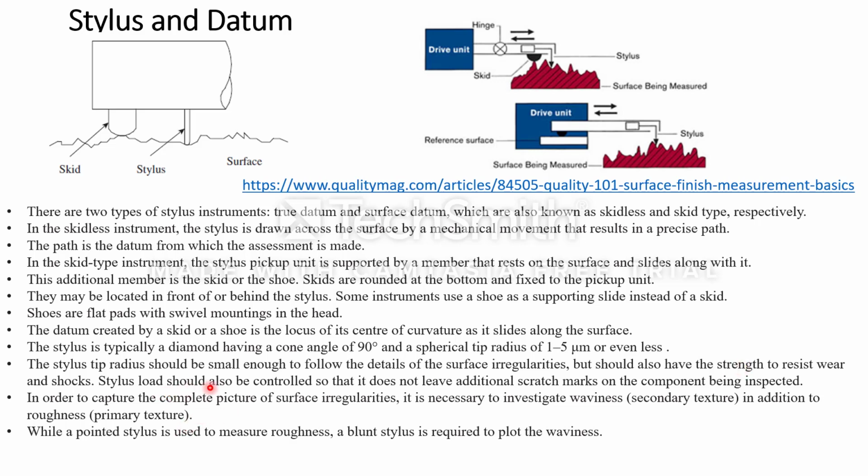Stylus load should also be controlled so that it does not leave additional scratch marks on the component being inspected. While I am inspecting this job, if my stylus applies too much pressure, there is a high chance that it will leave scratches and damage my job.